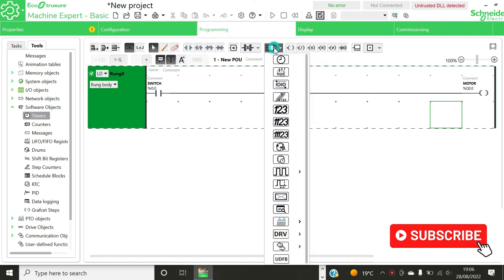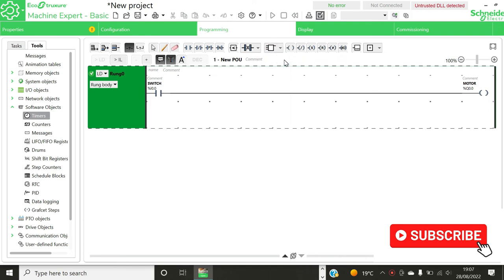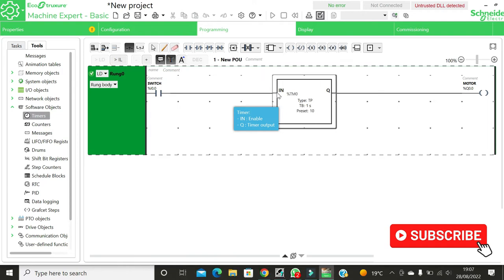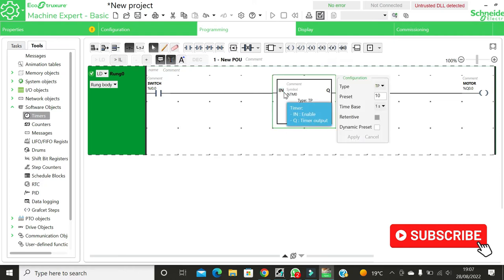Then you click on this icon here and you select timers. When you move your pointer across the screen, you can see it moves along with the timer. You can then locate it where you want, and then you drop it. Then when you click on it, there is a dialog box which appears. It has type, preset, time base, retentive, and dynamic preset. Here on type, this is where you actually set the type of timer you want it to be. So I click on T on.